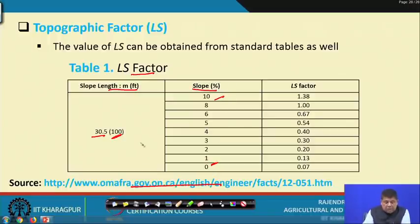If the length is 30.5 meters and slope is 0, that means horizontal, then the LS value will be 0.07, whereas if the slope is 10%, then this value will be 1.38. So, as the slope increases, the value of the LS factor also increases.